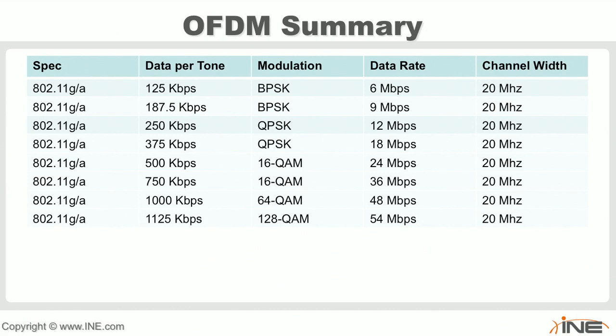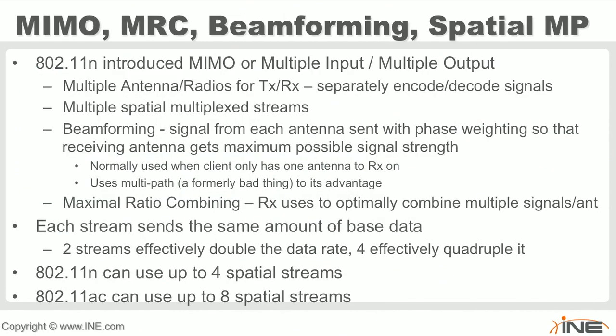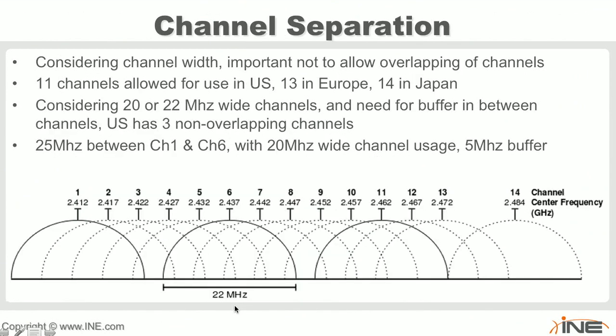Then we're 8 timesing, or at least 4 timesing, the maximum 802.11n channel width. And then we also have at least 4 more antennas than 802.11n can support. So we're sending 4 times the amount of data with 4 antennas, twice the amount of data. So that's 4 times 2, we're at 8 times.